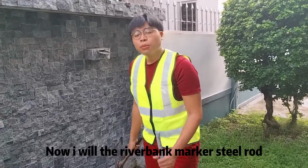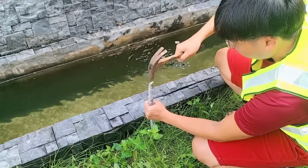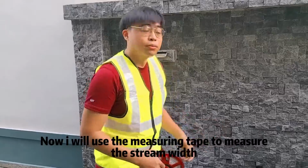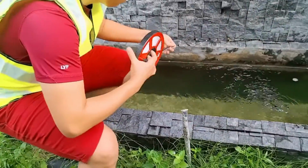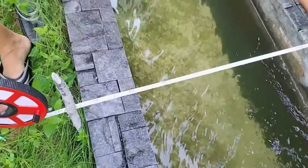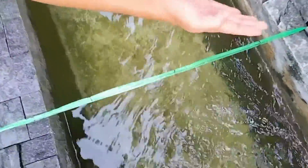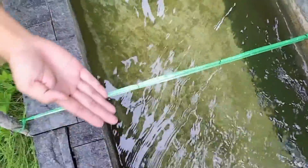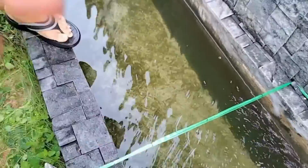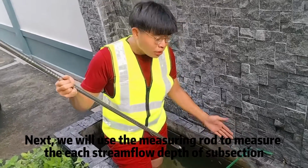Now I will use the riverbank marker steel rod. Now I will use the measuring tape to measure the stream width. Okay, next, we will divide the stream cross-section into numerous vertical subsections. Okay, next, we will use the measuring rod to measure the stream flow depth of each subsection.